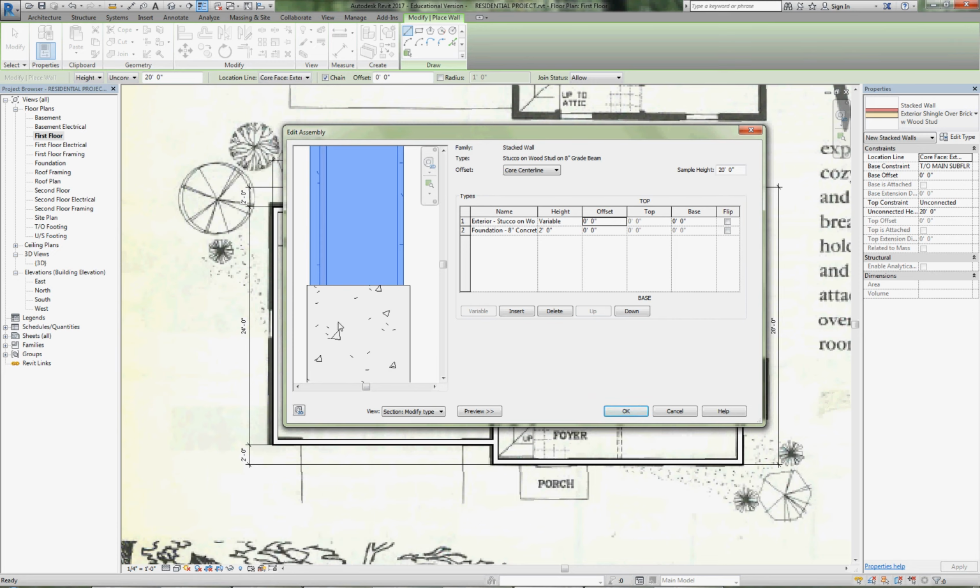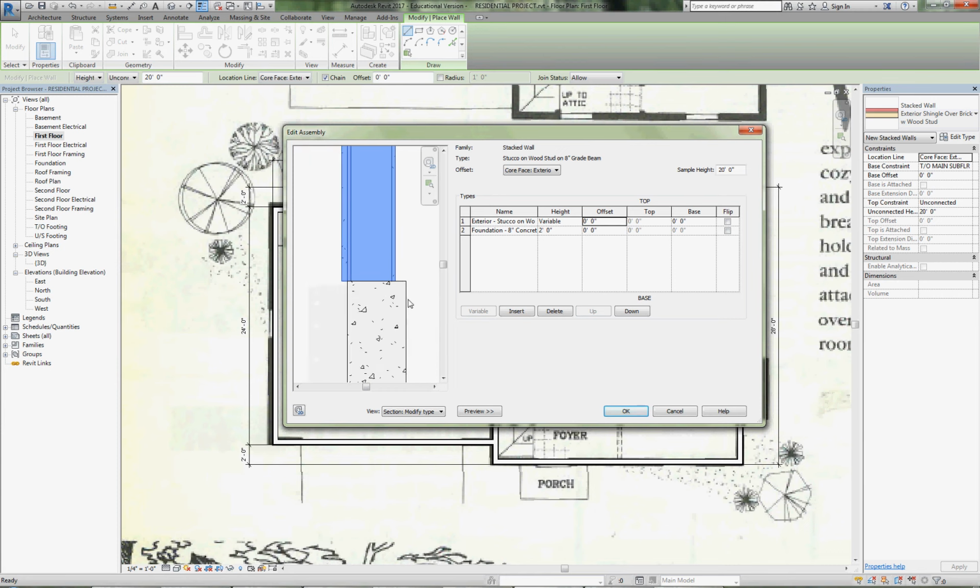Now we can calculate what it is, and I'll tell you what's happened so far. They have lined up core center lines, and that's okay. We're going to leave it at that. You can change it, but if I swap in here, we could calculate what to move. If I do core exterior face, it's done automatically for us. Core exterior face. Click. I need to get off of that so I can zoom. There. So that's the quick way to do it. And what happened was it did an offset to match our exterior face.